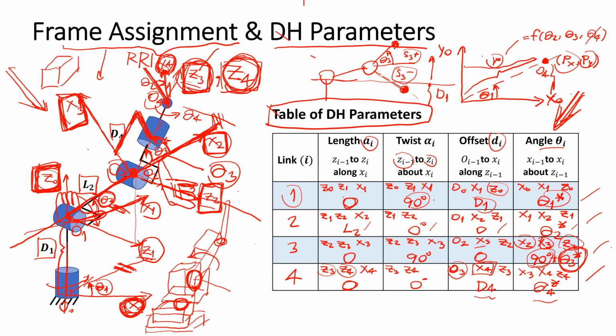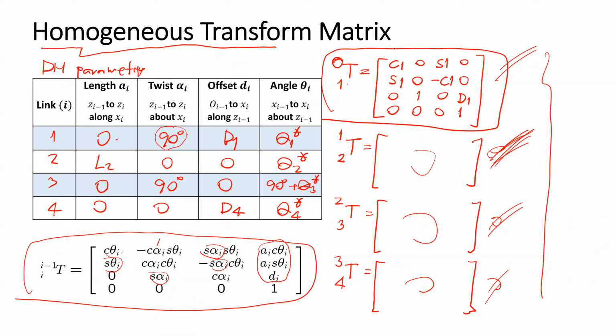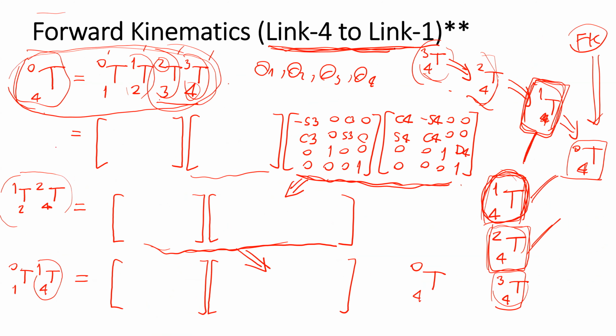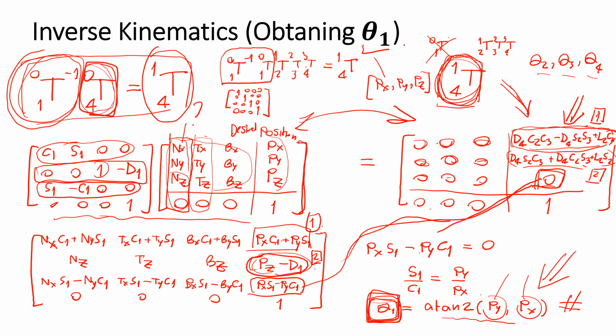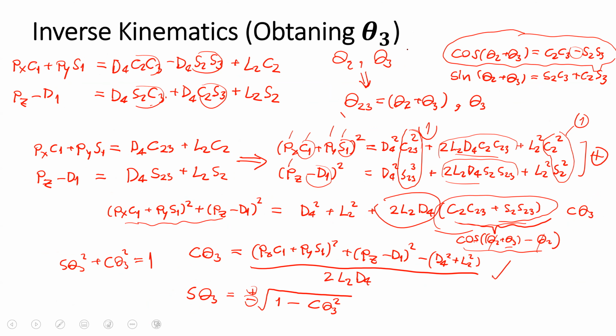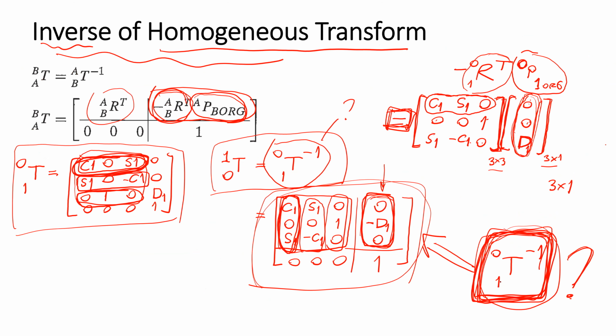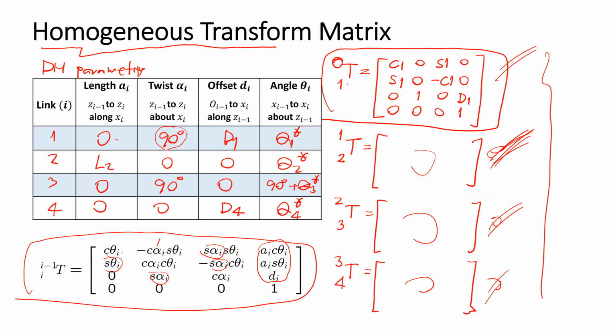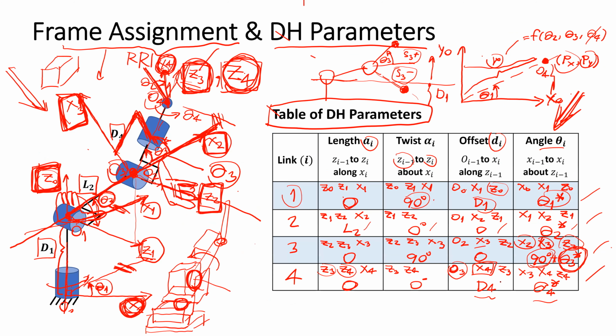And when you write the program to solve the inverse kinematic, you begin with theta 1. You obtain the theta 1 first. And for theta 3, we have two possible ways to get the theta 3. The cosine is fixed, but the sine of theta 3, we have positive and negative possible value. So yeah, in your program, you need to put the case for this.